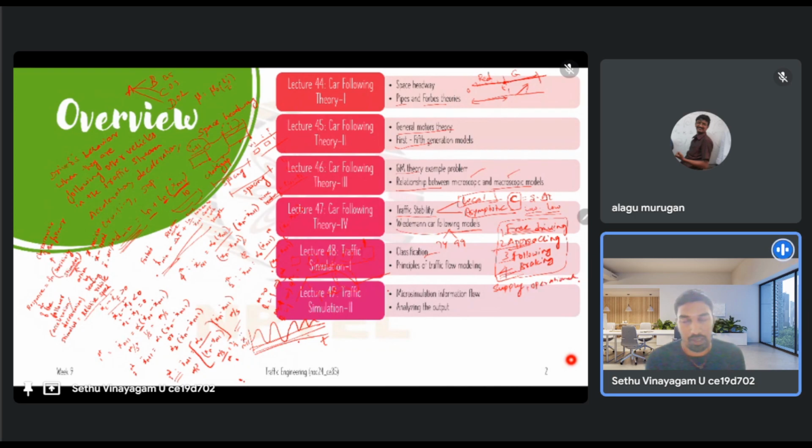Suppose you have a signal. What are the signal timing plans, right? How the signal is going to operate, and even if it is not a signalized intersection, sometimes you can have right turns permitted, sometimes right turns will be completely removed. Sometimes you have one-way operation or two-way operation of streets. All these are operational decisions, so they have to be pre-specified. These are within the control of the engineer or the traffic planner, so we can change them as per our decision.